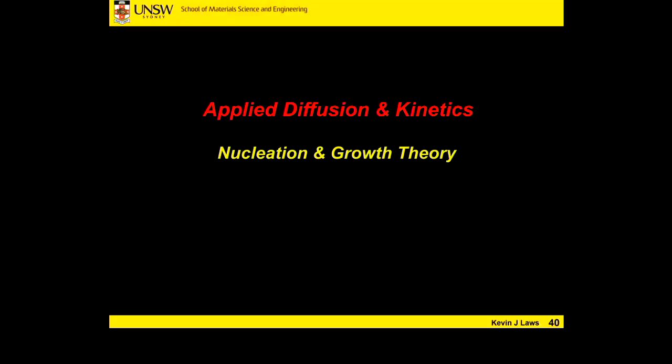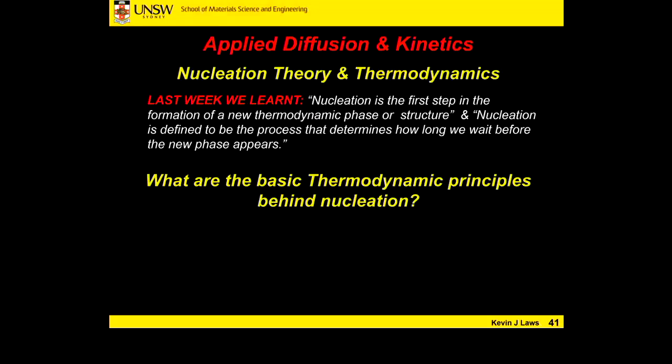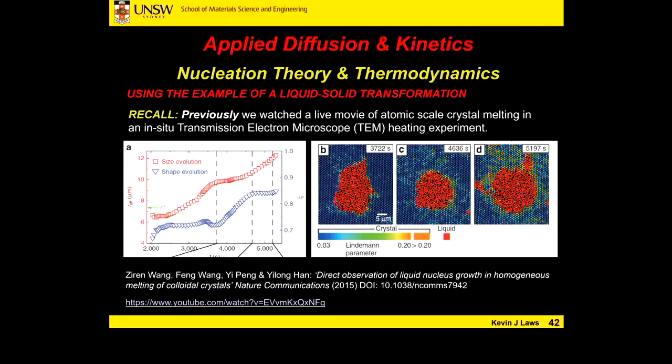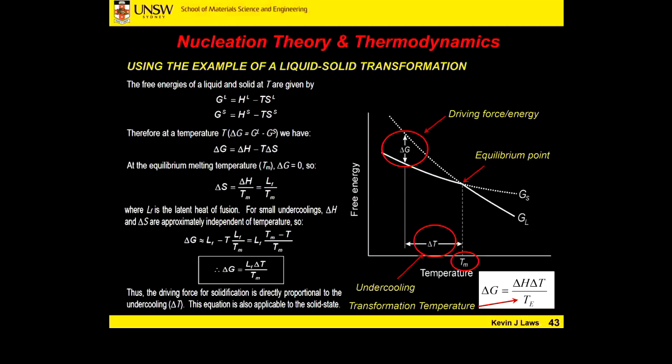So last Thursday, we had a little bit of a look at classic nucleation. Hopefully you recall we utilised our basic knowledge of thermodynamics, defining the difference between the free energy of, just as an example, the liquid-solid transformation, and how we define those, and how we can assign the driving force to nucleation being relative to our degree of undercooling, delta T. So the greater our delta T, typically the greater our driving force for nucleation.